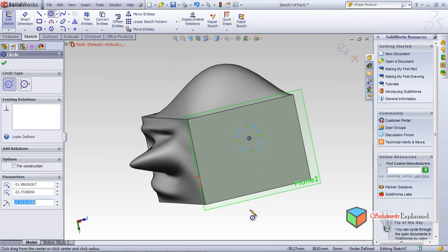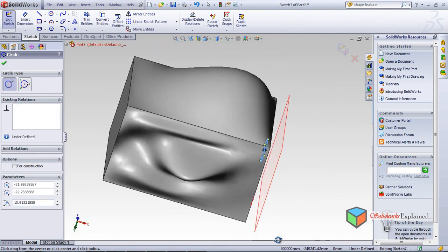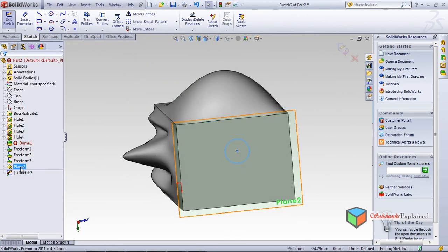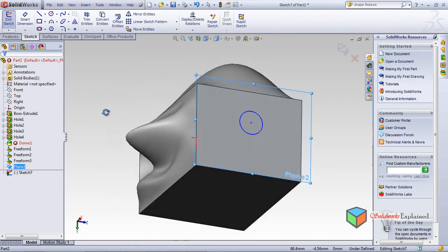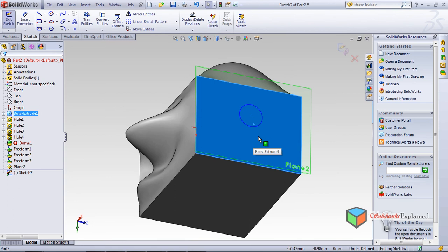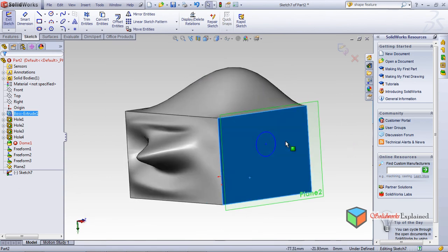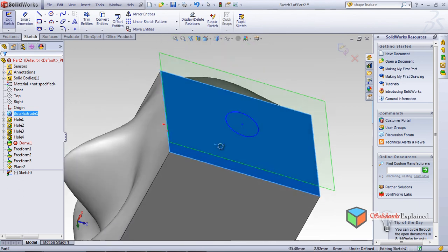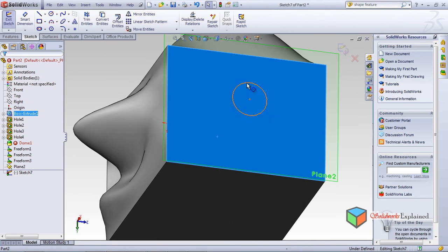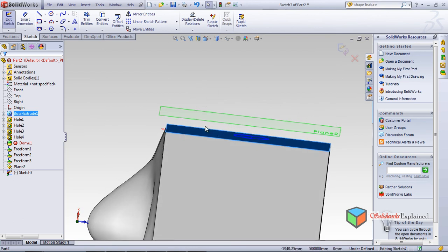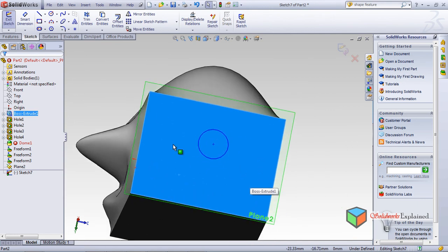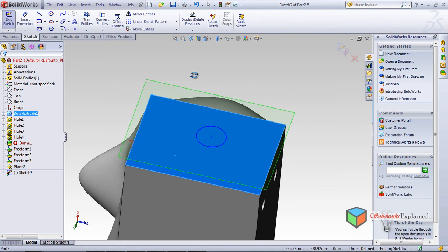Let's say I want to make a circle, so I made a circle. You start making on a plane. You make something on the plane, and then you use a feature called shape feature. When you use the shape feature, your dome at the top becomes a circle, and then it sticks to the edges. When you change the distance of this plane, the distance changes, but the shape remains the same. That's why the name of the feature was shape. But in your new version, you cannot really find it.